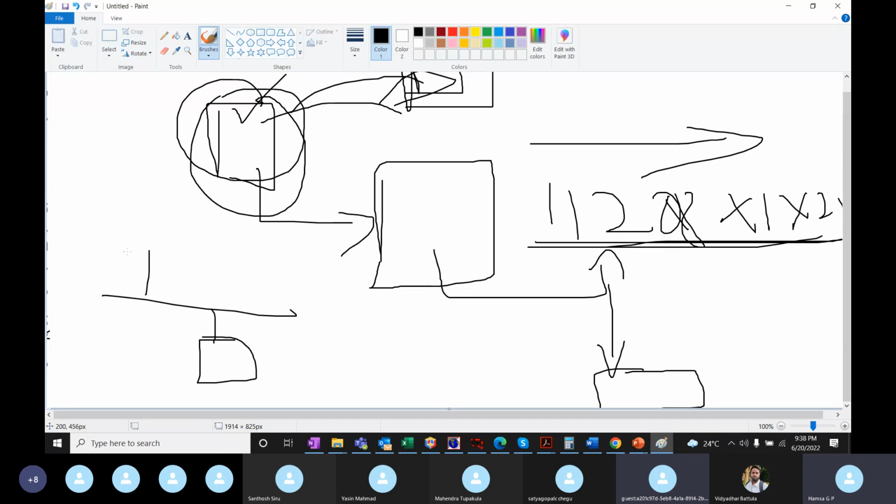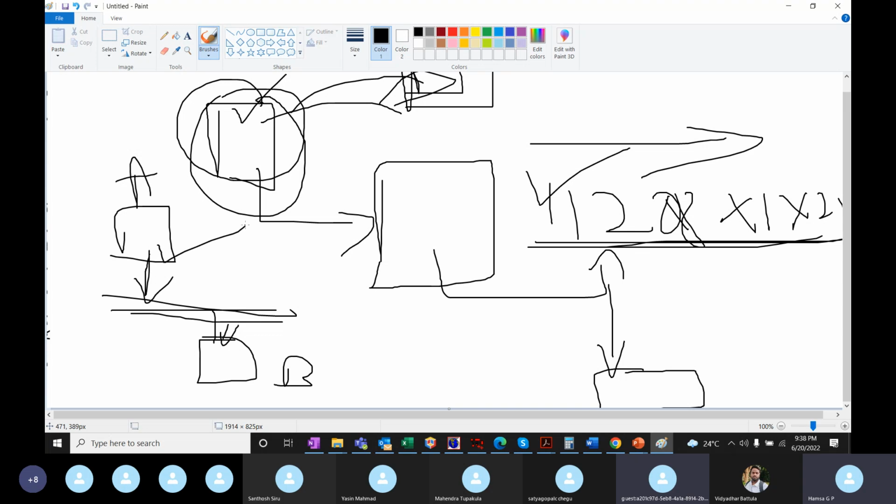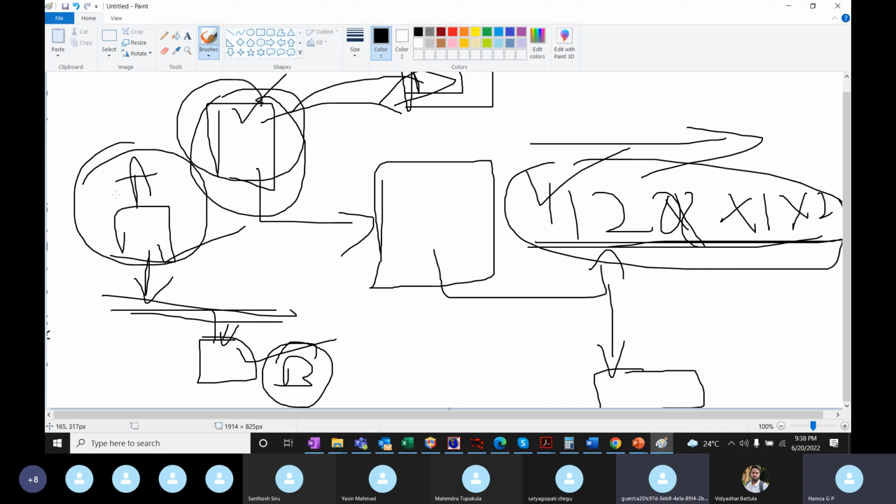I'll write it down like this so that it's easy for you to understand. ECU A, ECU B. ECU A sent this information on the bus and it is accepted by ECU B. How it is accepting, we will see later. But assume now ECU A is sending the data to ECU B, and ECU B accepted that information completely and started processing. So how exactly does ECU B confirm that this is the proper data received from ECU A? There should be a check, right? There should be some confirmation for ECU B before it completely accepts the input from any other ECU. Correct, right?